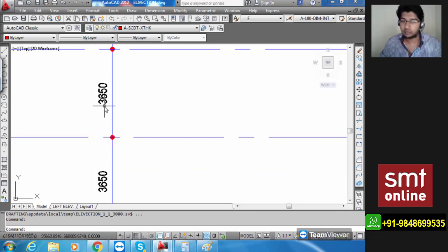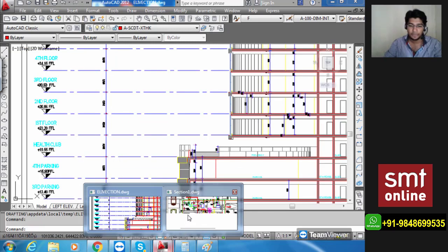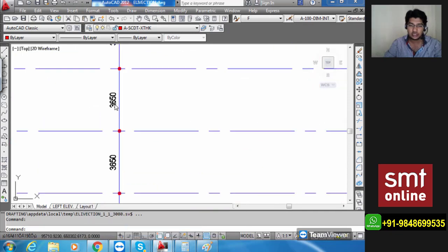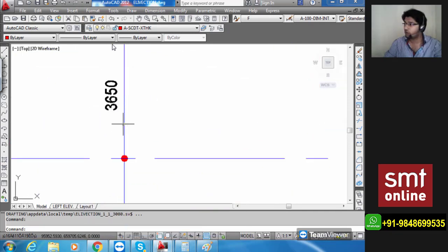So we can even take a little more. I am going to make some modification to this because we are focusing on looking at our internal services. So I'm going to increase the false ceiling height from 2 feet to 4 feet. Right? So now what I'm going to do is coming back here, total offset, it is currently 3650. I'm going to take that off 3800.